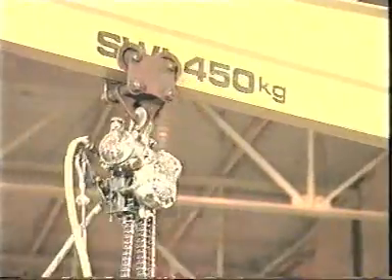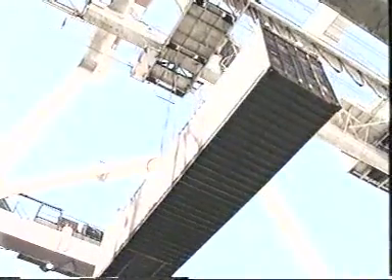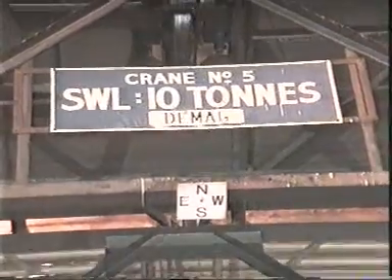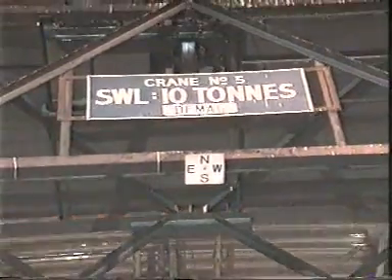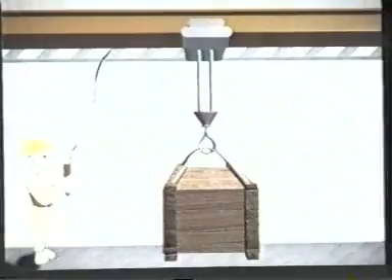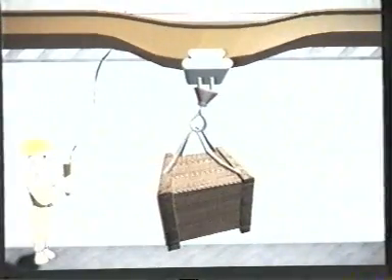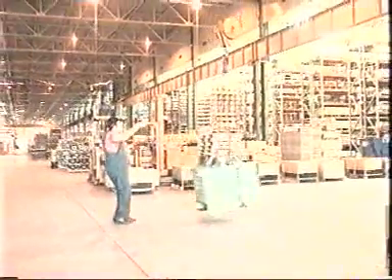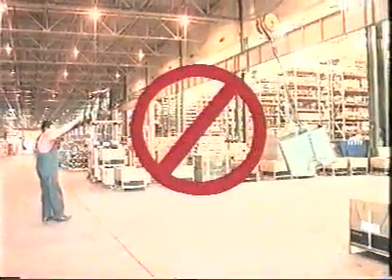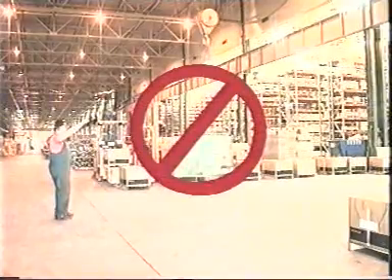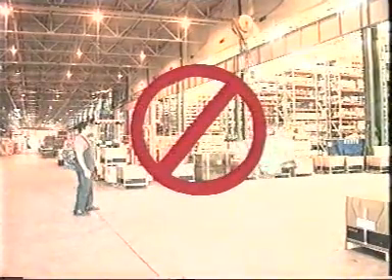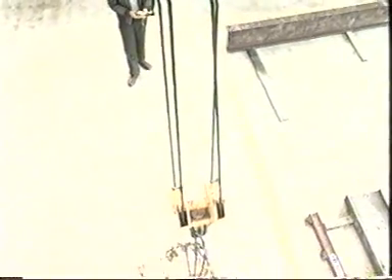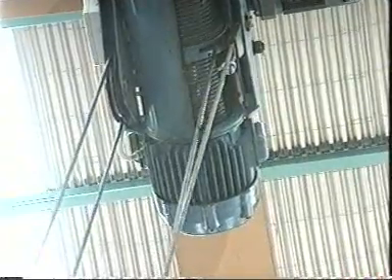It's important not to exceed the rated working load of the crane. The safe load capacity is the maximum load which should be lifted. If this load is exceeded, then it could lead to mechanical and structural failure. Always remember, incorrect operation of your crane can result in overloading, even though the weight of the load is within the crane's rated capacity. For example, shock loading by stopping or starting too quickly can result in an overload.